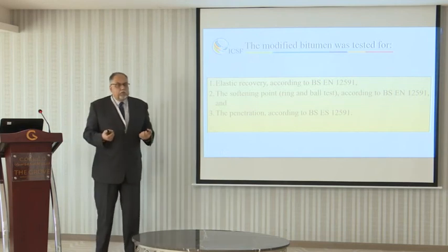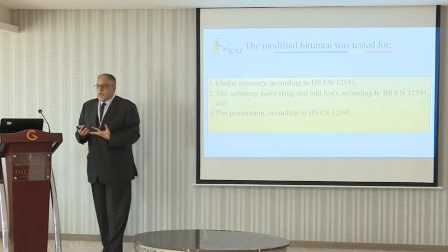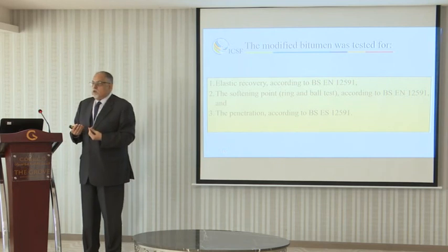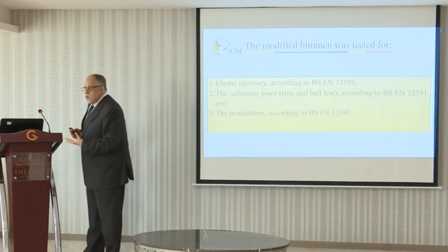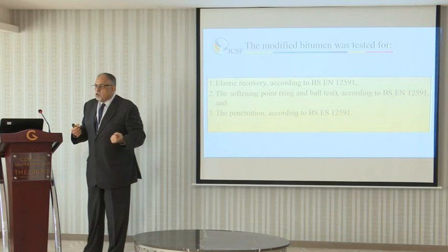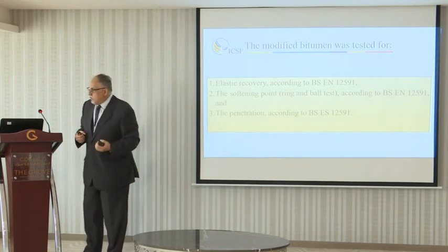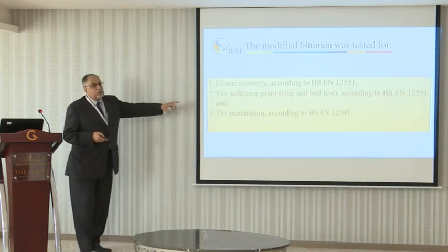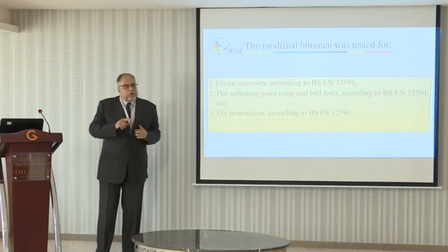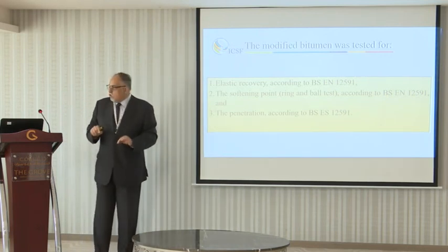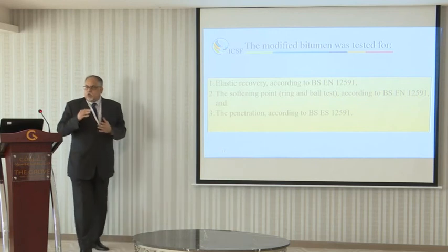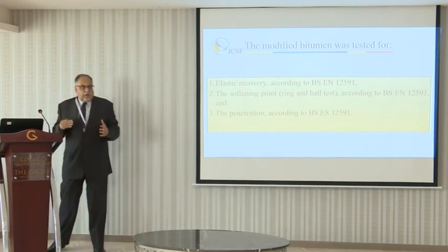You know, if bitumen is too tough and too brittle, it cannot be used. That's why it should have a certain elasticity. And also the softening point, which is related to the viscosity of the bitumen type, because we have different bitumen types and grades.